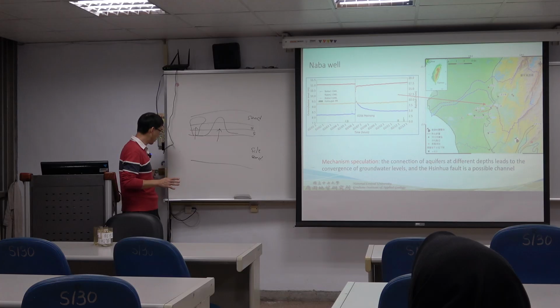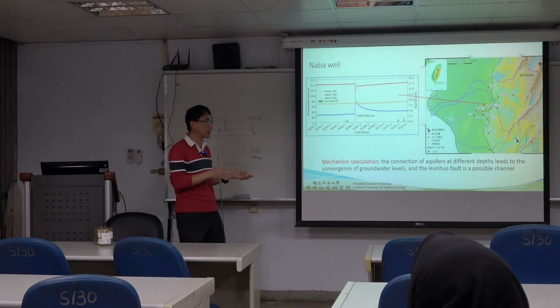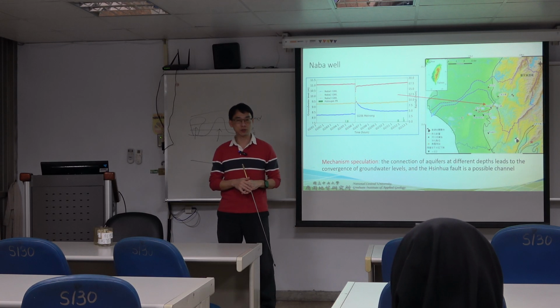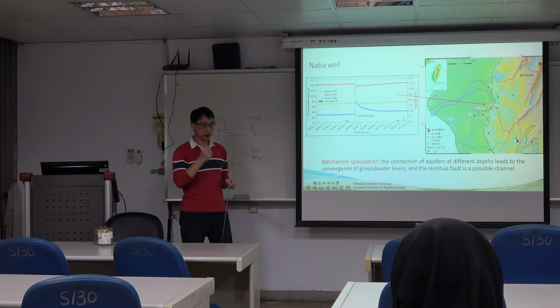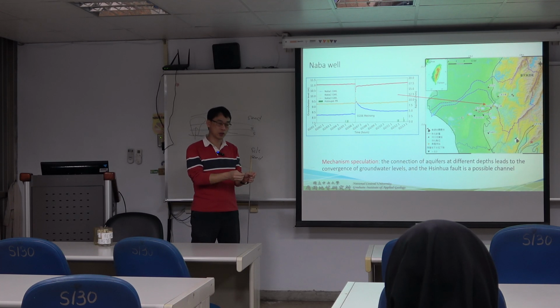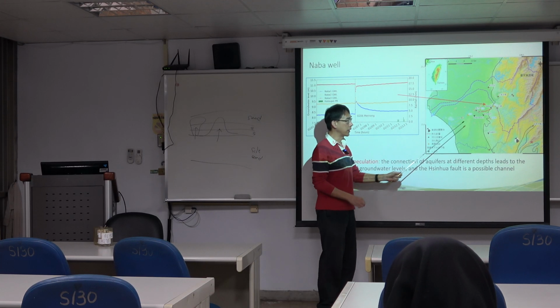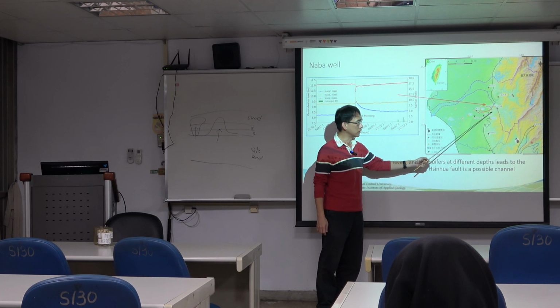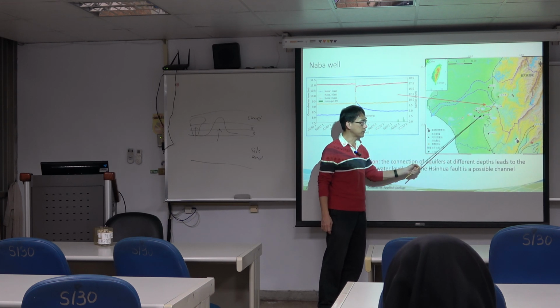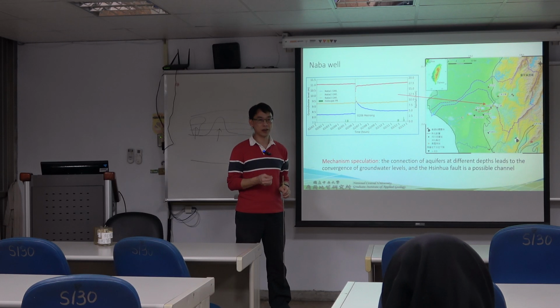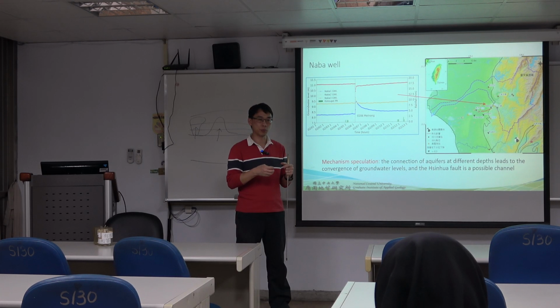So I want to emphasize that liquefaction is not only what we see in these kinds of places. Liquefaction can be much larger and widely distributed, but we only see the open channels where the liquefaction erupts. As I mentioned, this one is the Xinhua fault trace. If there is surface damage or surface rupture, you will commonly see liquefaction occur, because there are open channels to let the excess water pressure dissipate. So you see liquefaction in that area.